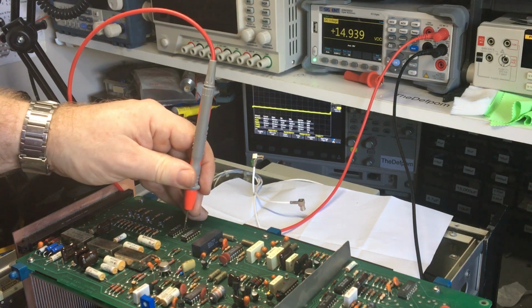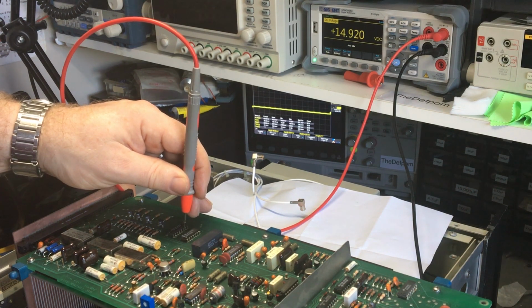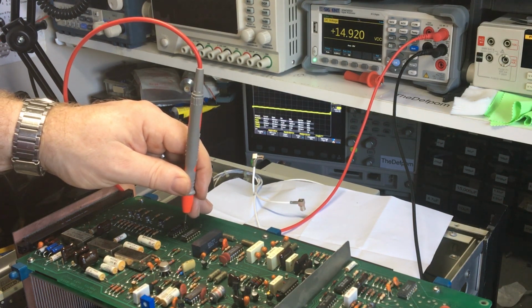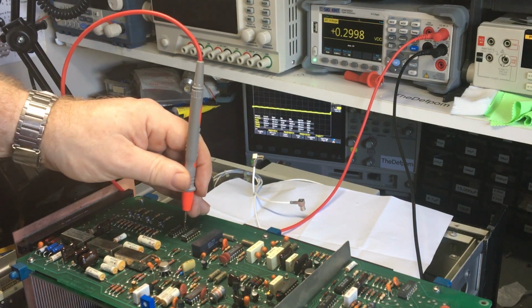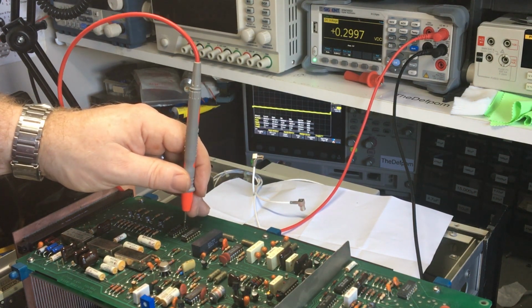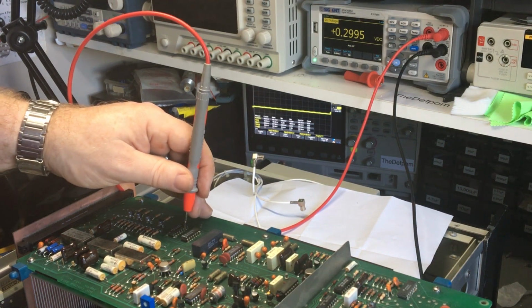Let's go to the next pin, pin 6. Start at the bottom again, 100 Hz. So that's high on 100 Hz. High on that one. Must be feedback voltages. And on 10K it's low. Yeah, it must be voltage feedback. Right, so it's definitely low on 10K.